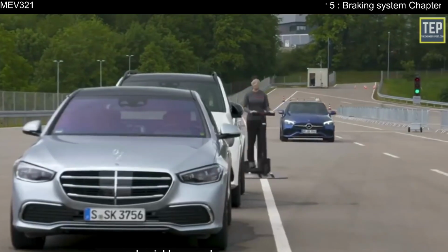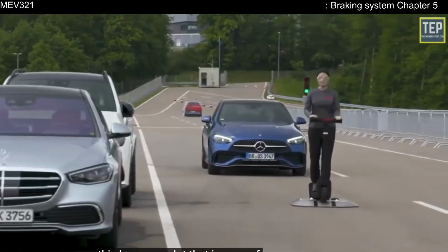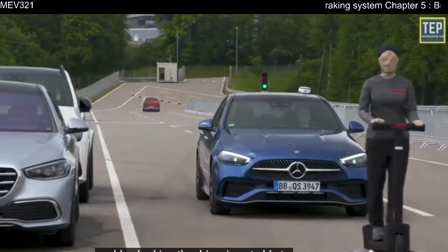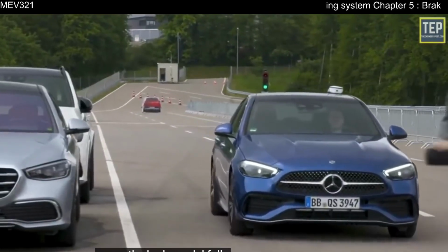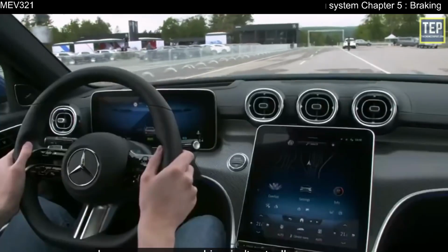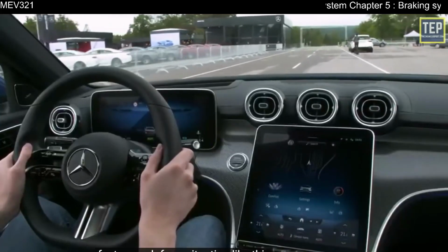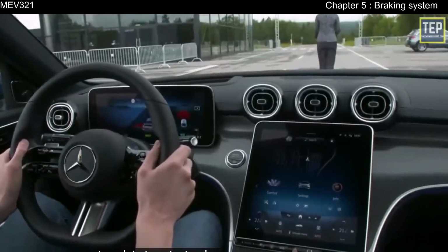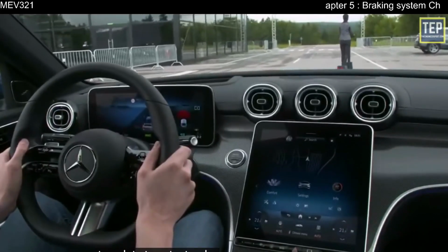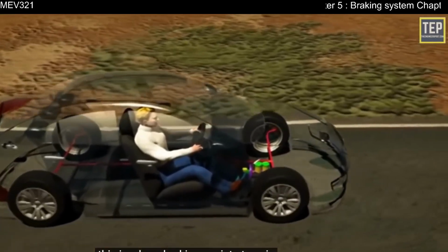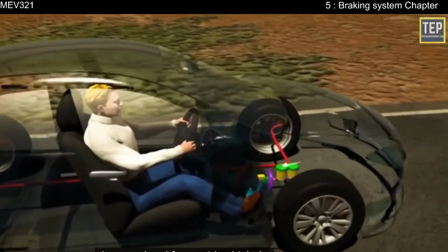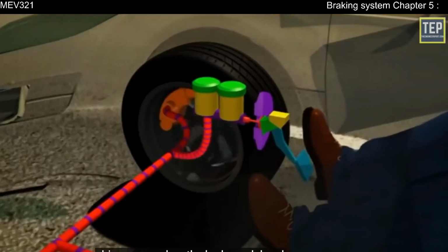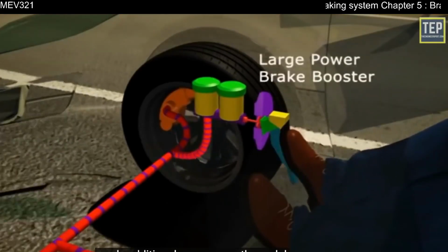This happens a lot: in case of sudden braking, the driver is not able to press the brake pedal fully. An average driver isn't actually fast enough for a situation like this, where a millisecond of delay can translate to catastrophe. This is where brake assist steps in. With brake assist, the electronics sense the speed and force with which the driver pressed on the brake pedal, and apply additional pressure on the pedal for full braking.